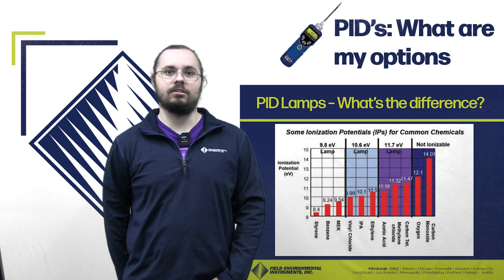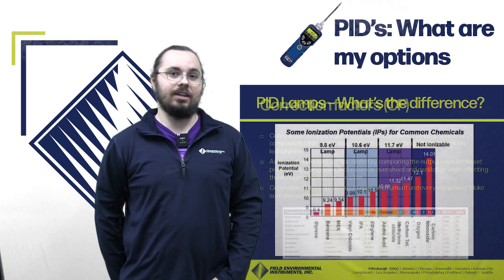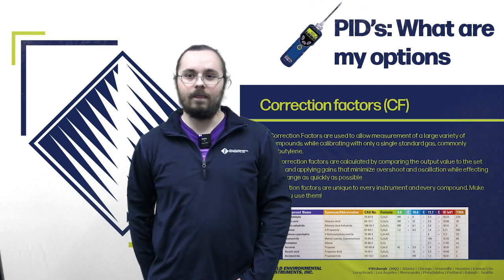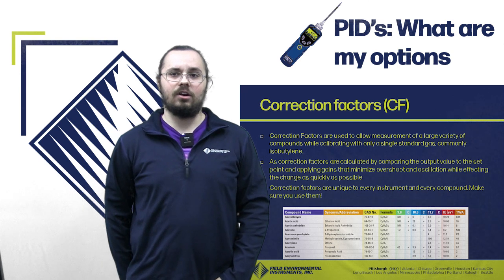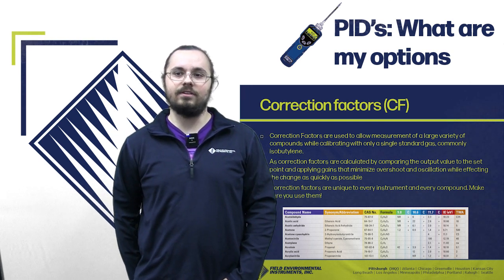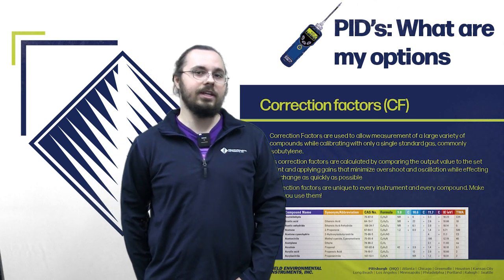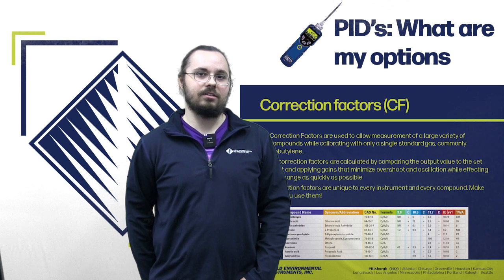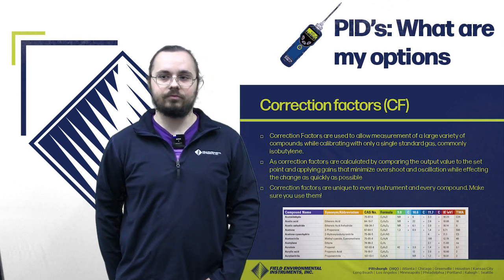Another thing you'll commonly hear when dealing with PIDs is the correction factor. Correction factors are basically used to allow the measurement of a large variety of different compounds while only needing to calibrate the unit with a typical standard gas, isobutylene.